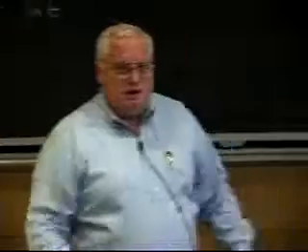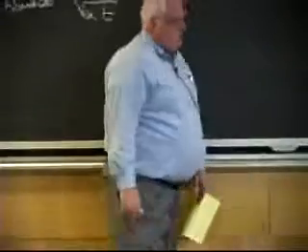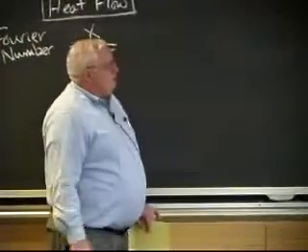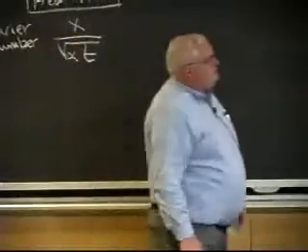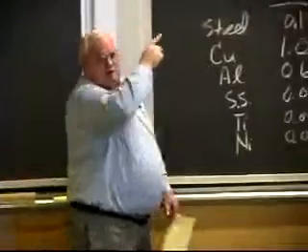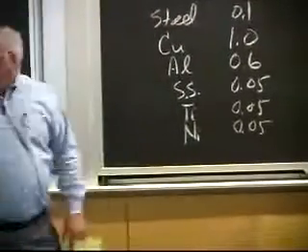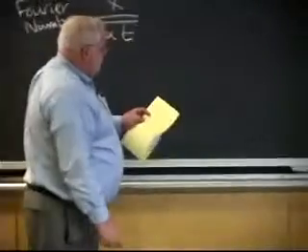In fact, the only table I know of thermal diffusivities is volume 6 of the Metals Handbook in the very first couple of pages. I may have given you that handout, and that's because I wrote that thing. I'm always sitting there asking, what's the thermal conductivity of this or that? So I one time had a student go through it, calculate it for me, and made the tables and put it in the handbook. But in general, most places will give you thermal conductivity, density, and heat capacity, and then you've got to calculate it out. And it's much easier to just know these types of things.